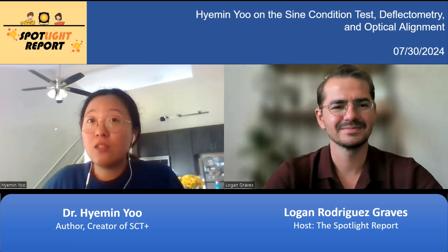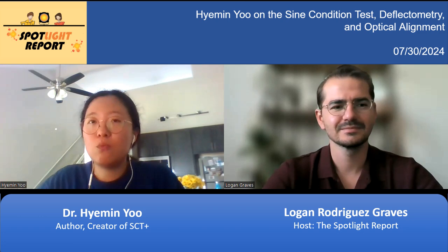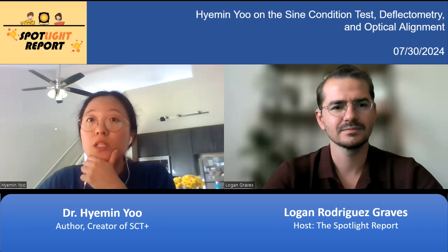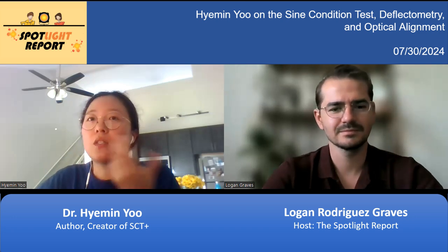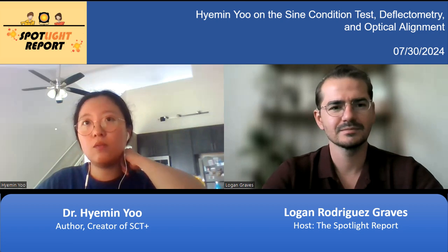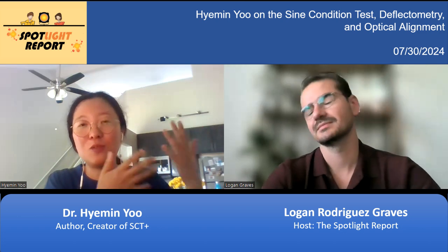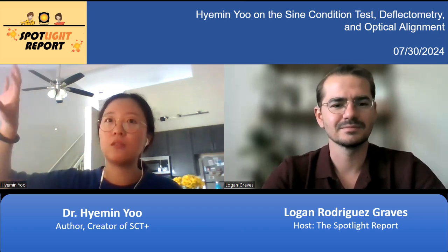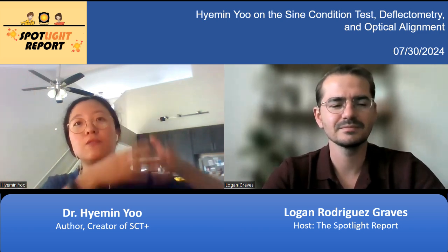There are some people complaining that deflectometry is an awesome concept, but it's really sensitive and you need a high precision geometrical calibration. So we only care about high spatial frequency wavefront errors, or there are other studies related to deflectometry asking, how do we improve this geometrical calibration? Is there a better way to deal with this problem? So the mainstream was either using deflectometry for high spatial frequency wavefront error, or finding a better way to do geometrical calibration.